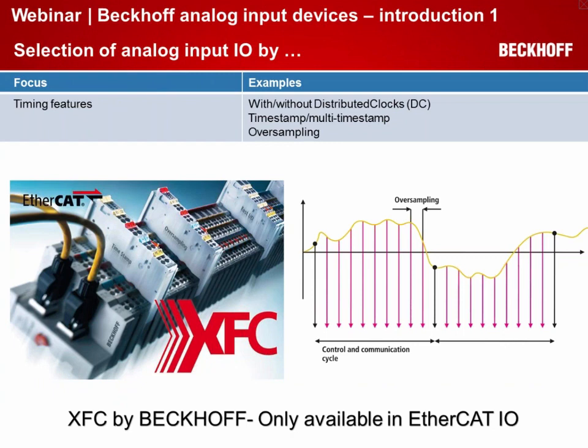Oversampling means that in our world the TwinCAT task, the program, is always running in a hard fixed cycle time. As I said, for example, 1 millisecond cycle time, the complete program should be run in one cycle. When you have big programs, you can make more tasks. You can make a 100 millisecond task in addition to a very fast task and a super speed task. So you can combine different cycle times on one IPC, and such a task will then trigger the field bus and gather the analog data.